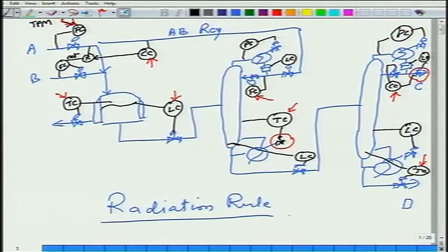If there is too much benzene coming in the product, I'll increase the temperature set point here, right? So even though my throughput manipulator is at the feed, by adjusting these temperatures and compositions, I am ensuring that my product quality is 99 or 99.9 or whatever it is that I want it to be.